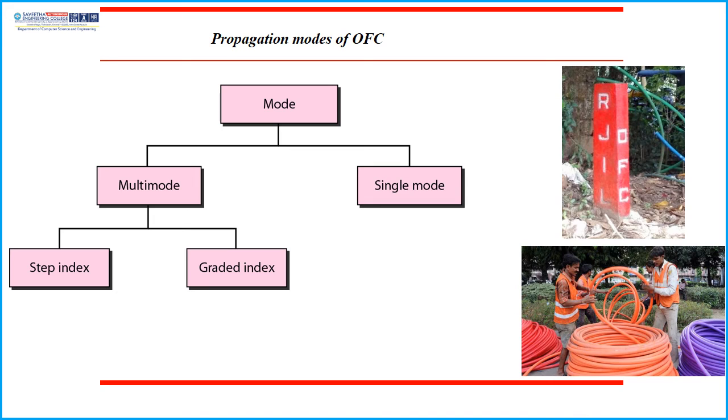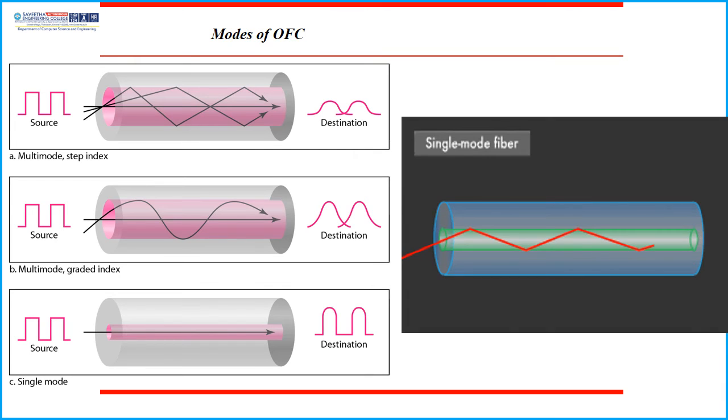These fiber optic cables work in two different modes. The first mode is multi-mode, the second mode is single mode. We will be seeing the modes in the next slide. In general, single mode fiber is used for long distances or higher bandwidth needs, and it uses a single laser light as its light source, whereas the multimode fiber uses an LED as its light source, and is used for shorter distances or less bandwidth intensive applications.